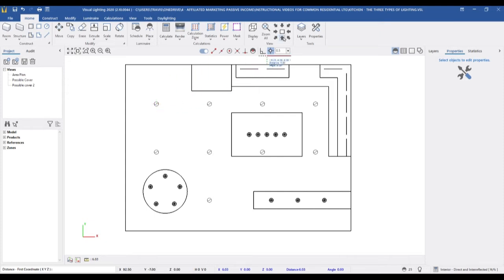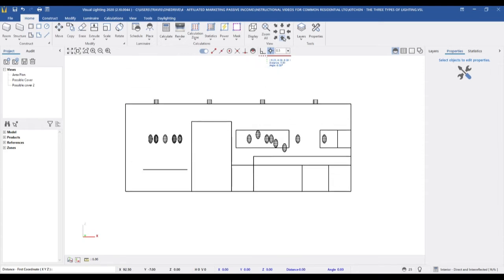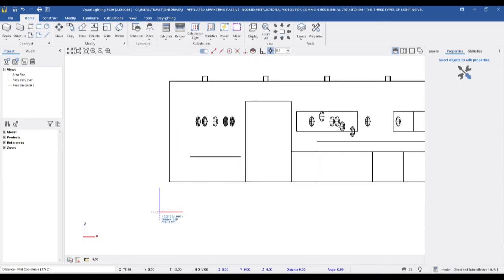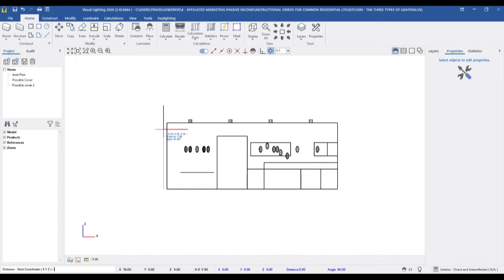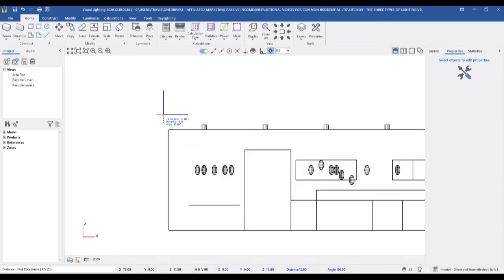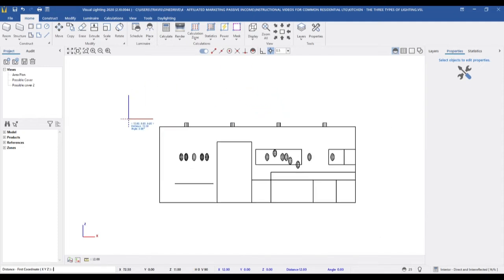So to make things easy, for our purposes here, we'll say that the spacing criteria is 1. What this means is if your light is 12 feet from above ground, or AFF, which is above finished floor, then the max you can space these fixtures from one another without having any gaps is 12 feet. So you basically take your ceiling height, or the height between the surface you want to light and where your light source is going to be, and you multiply that difference by the spacing criteria to get your max allowed spacing.